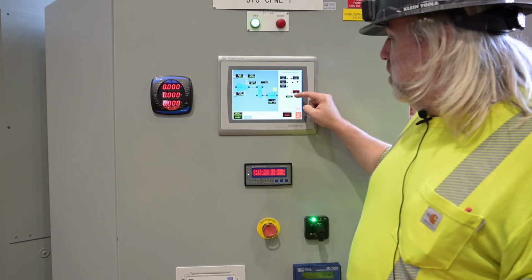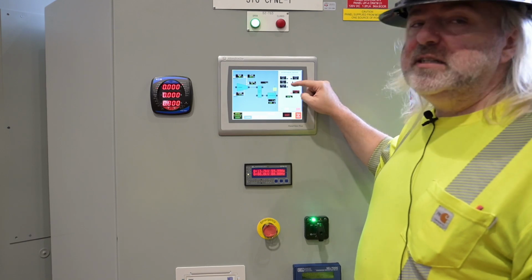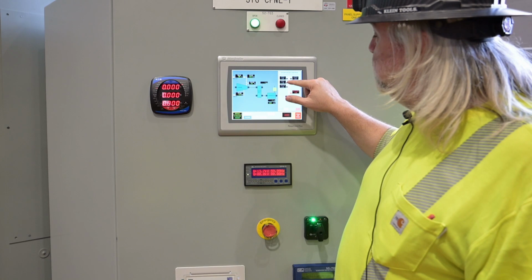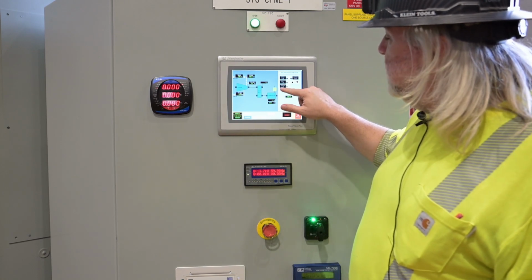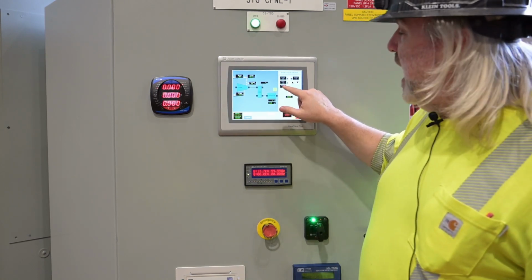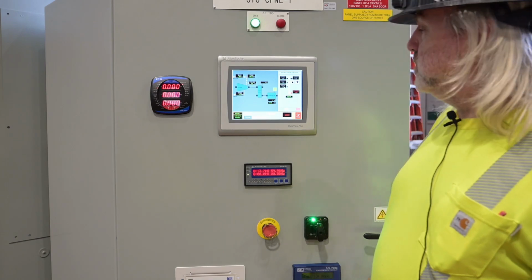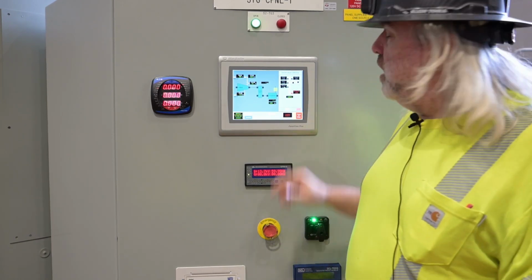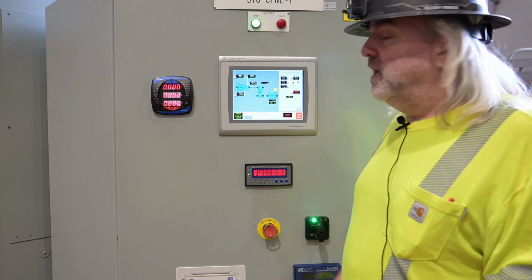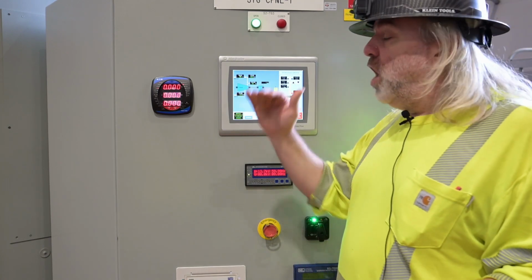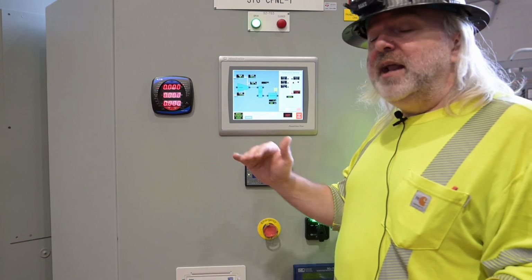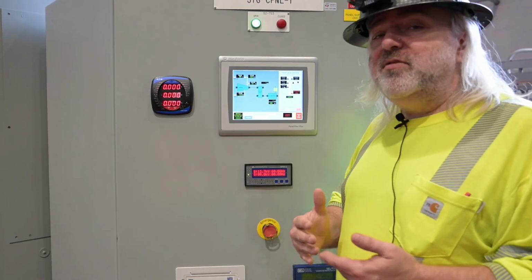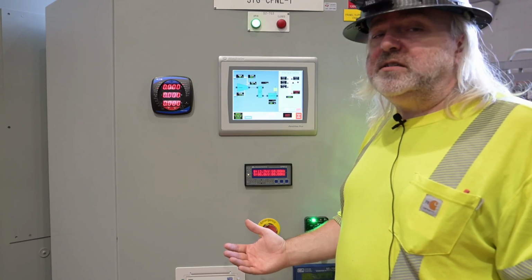Again, low signal. So whatever the lowest signal is on the bus will control the valve. So in this case, if exhaust pressure is 4.26 and kW is 0.29, kW will control that valve. In addition to that, we have a valve limiter, which once the system starts, the valve limiter is always on the bus. The valve limiter can be used to lower the valve output in case of any type of troubleshooting or diagnostic activity. Other than that, there's no need to use the valve limiter for any reason.